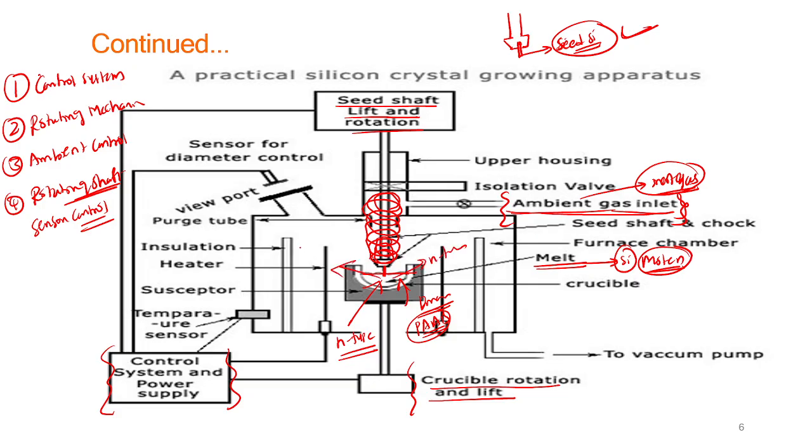Suppose you want p-type material, that means trivalent impurities. The earlier ones are pentavalent impurities. Trivalent impurities are, for example, boron. If you add boron, then when you are dipping and slowly moving, you get p-type material. Like this, you can make n-type and p-type material, which we can combine to make a PN junction diode, and use in MOSFETs and all those things.